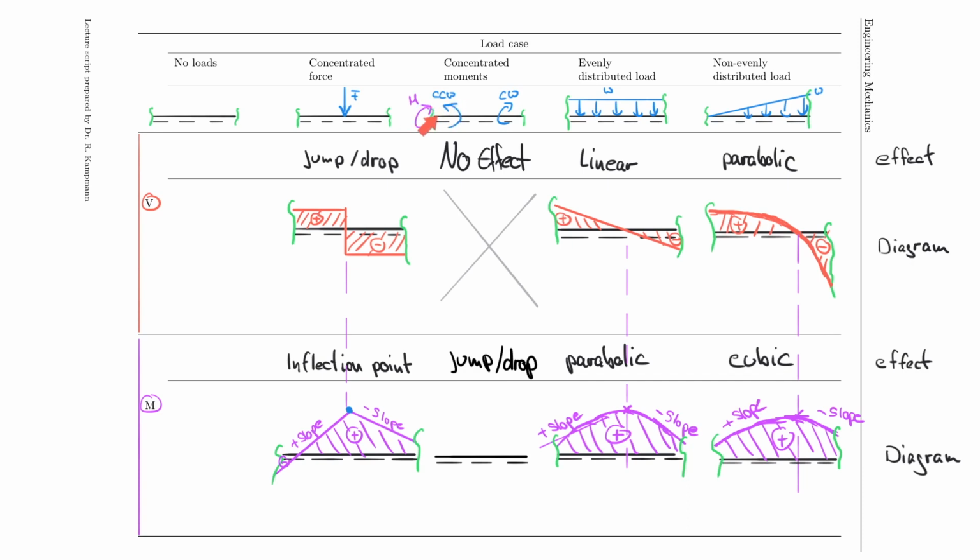However, if I cut the system here and then look at this portion of the system, so I move this purple arrow up to here and then look at only this part, then you see that they actually rotate together. So you would end up with a negative jump here. So symbolically, how that would look like would be with a jump that has the magnitude of the moment.